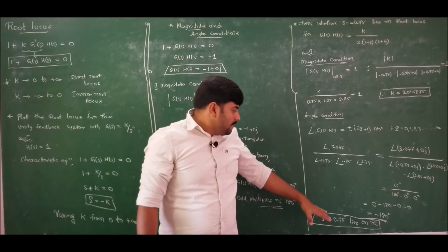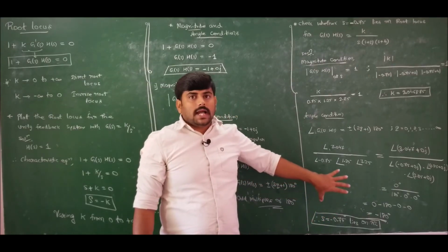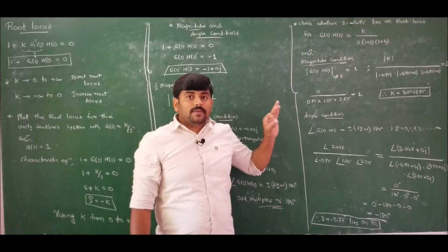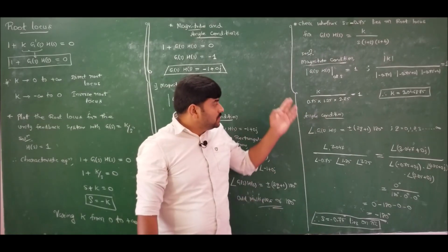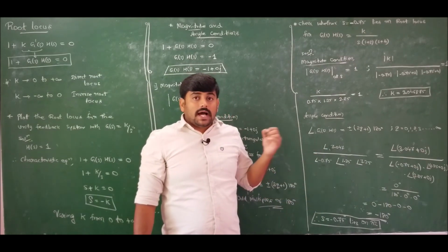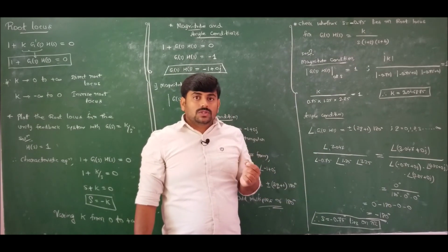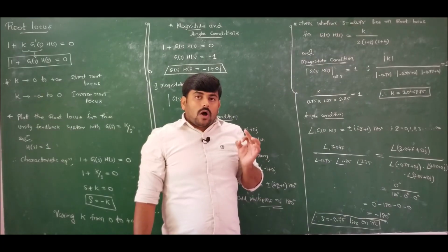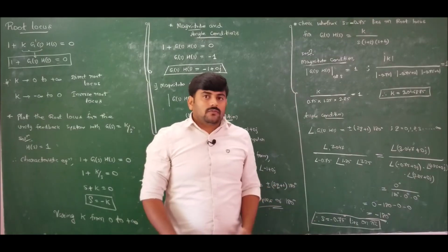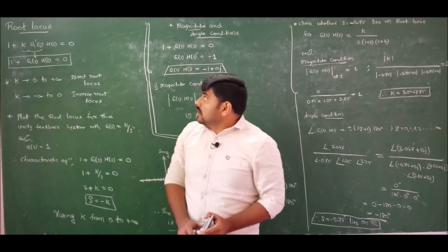So using the root locus technique I can determine the roots of higher order polynomial equations. Using the root locus method, angle condition and magnitude condition, I can determine the roots of higher order polynomial equations quickly. So this is one more advantage of the angle condition and magnitude condition of root locus.